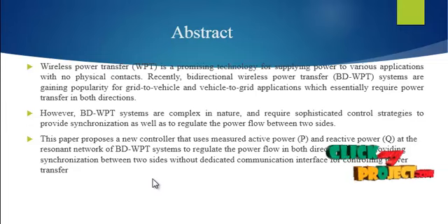The current source WPT system allows bidirectional power transfer between the grid and any number of independent loads, which is more suitable for V2G applications, and grid-tied bidirectional converters are employed to control the grid current as well as maintain a constant and smooth DC link voltage for the proposed bidirectional system. This is the example for a single pickup load.